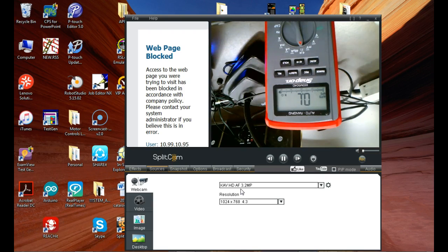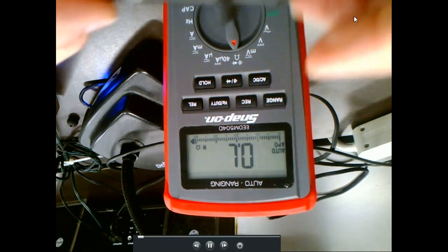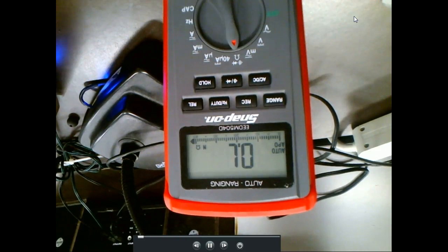This is a Cat 3, 600 volts AC or DC. It's Cat 2, 1,000 volts DC and 750 volts AC. So even though this lead has a Cat 4 rating, the problem is that rating is not with that metal rod exposed. Let me get it over so you can see it. Let me put it full screen. So it's with this metal rod out here covered up.